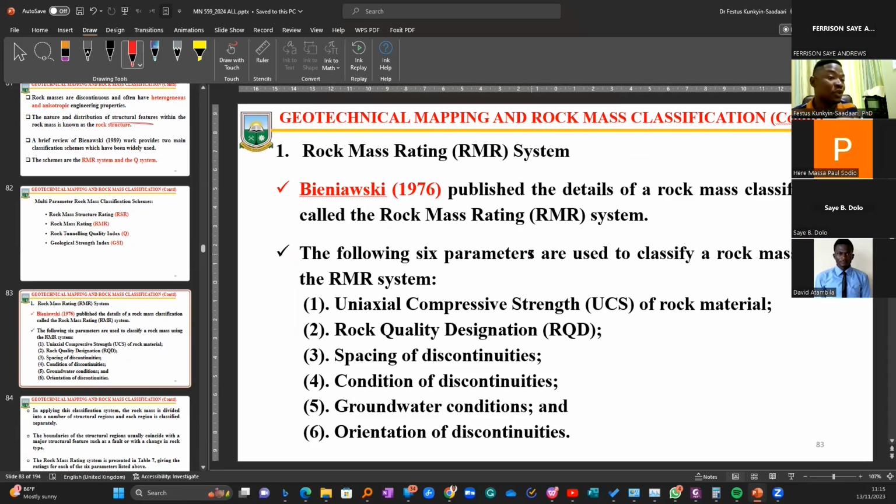So he was also a smart dude, you know. He decided to check those properties that other people have proposed, the rock mass classifications that people think are good, and the mechanical properties that we think influence the rock the most. So his principle will talk about the uniaxial compressive strength, which means he has covered the mechanical property of the rock. Then he came to the quality of the core, which is this. Then he goes to the geotechnical mapping to check the discontinuities visually, give descriptions and rate them. Then he adds that to his principle.